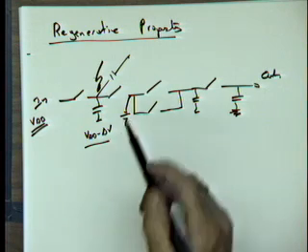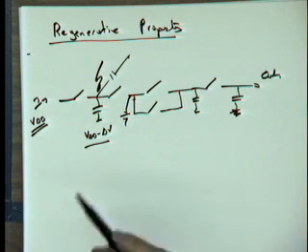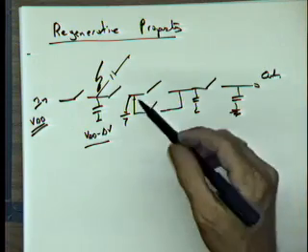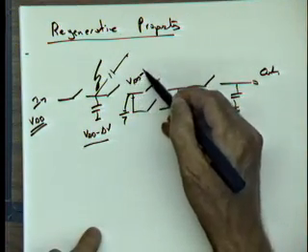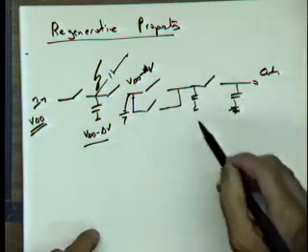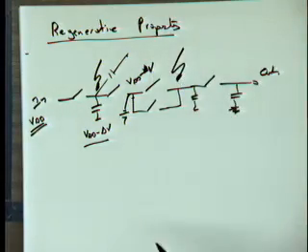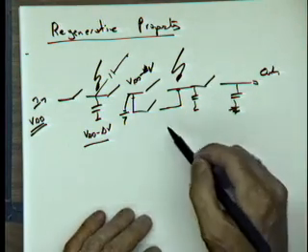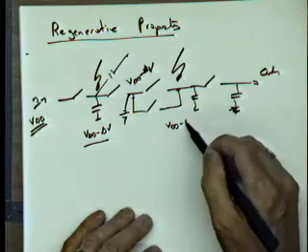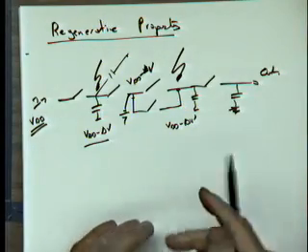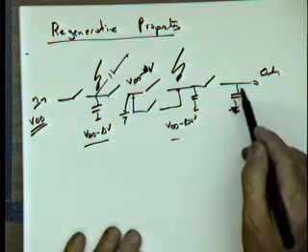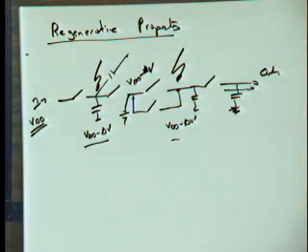But I lose some signal. Now, the next switch is not going to do anything about it. Actually, the voltage I'm going to pass is still going to be VDD minus delta V. Now, suppose I go further in the chain, I have another noise source, which again moves that value around. Maybe I now get VDD minus delta V prime, which is larger. I lose even more signal, and so on and so forth. You see that in a network like this, you never recuperate from anything bad that happens in the chain. This is an example of a non-regenerative network.